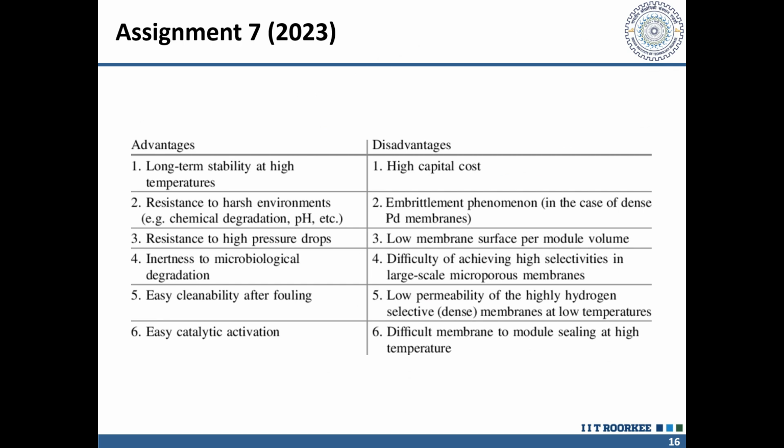So here are some of the advantages and disadvantages of inorganic membranes. The advantages are long-term stability at high temperature, because ceramics can withstand very high temperatures, and also resistance to harsh conditions, pressure drops, microbial degradation, easy cleaning, and catalytic adhesion. But the capital costs required are very high, and there's a major problem which is known as embrittlement phenomena.